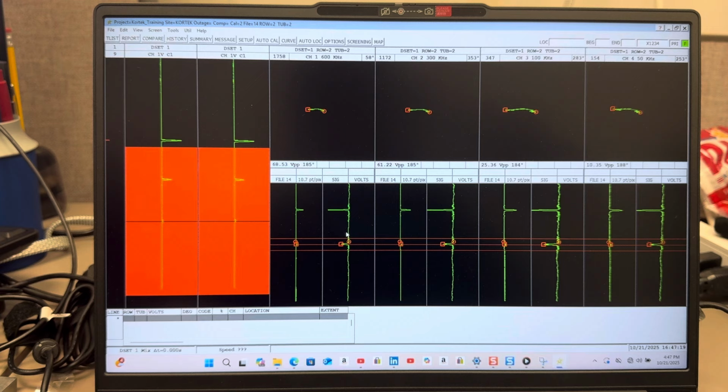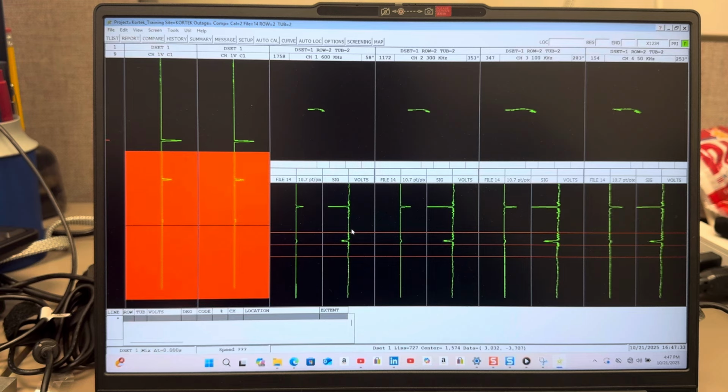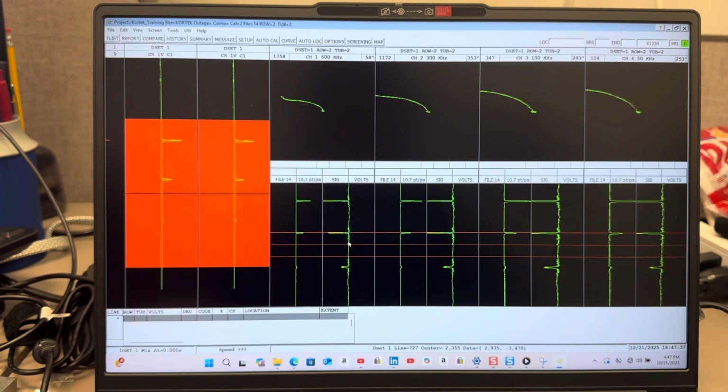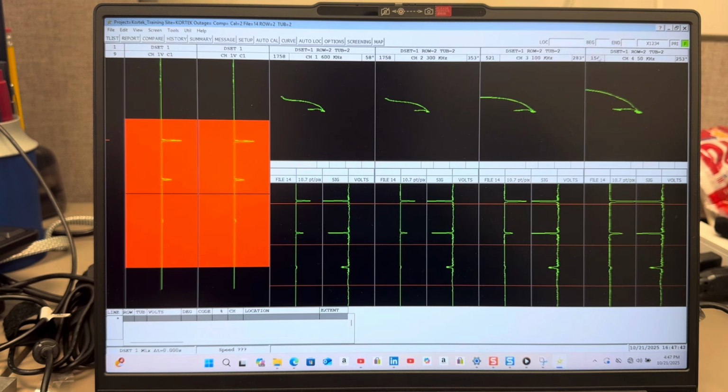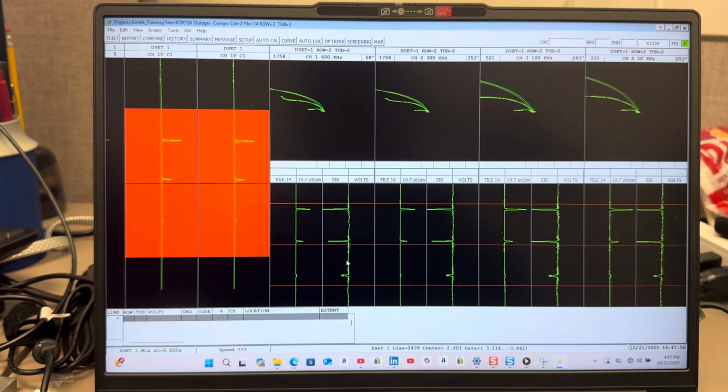The big difference with tubing is that because you're looking at flaws on the inner surface and the outer surface of the tube, you have to use a lot more phase analysis or different test frequencies to determine whether the discontinuities are ID initiated or OD initiated. Although you can't see it that great here, there's going to be some phase lag for the deeper notches. The biggest notch you see here is from a 40 mil, or 40 thousandths, deep surface breaking notch.